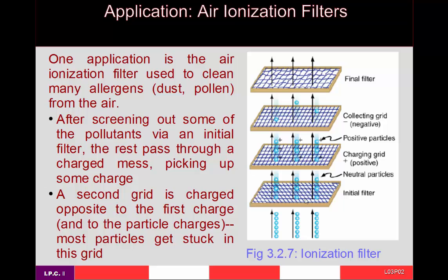What you really want is to have, say, 1,000 particles per cubic meter, or maybe 100 or 10. 10 is pretty dang good. That's a clean room in which you're doing silicon manufacturing and you have to put on a bunny suit to walk into the room.